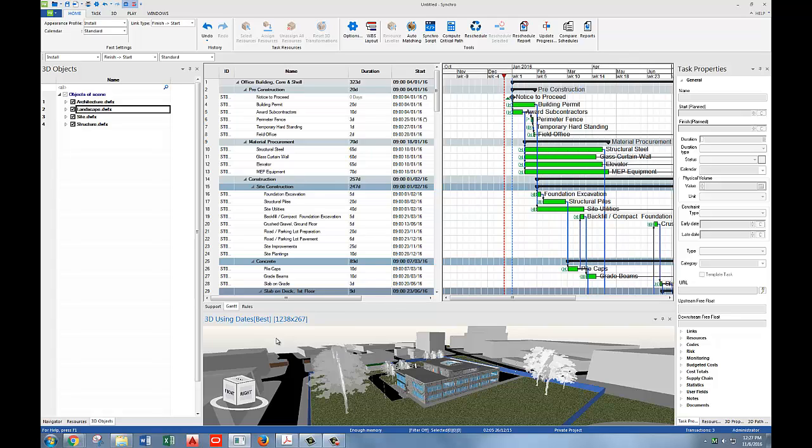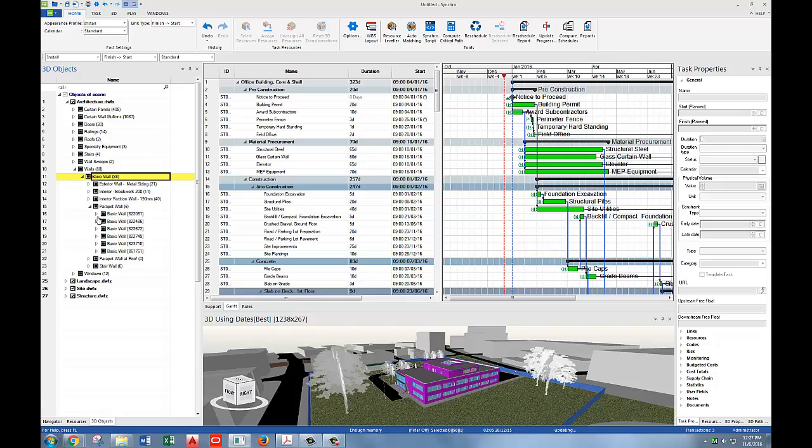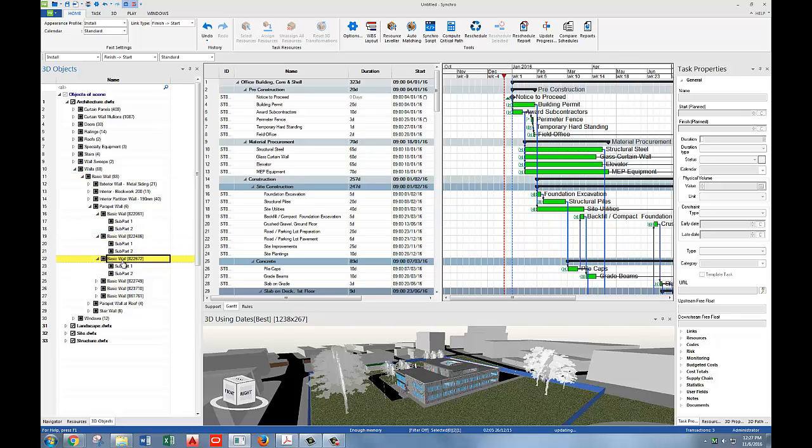So you should have imported your two new files. So over here where our 3D objects are, let's go to architecture, expand the walls tab, basic walls, parapet walls, basic wall again. So if we look right here, we can see that underneath each one of these basic walls, they have been given two subparts. Obviously, subpart 1 is the same as this subpart 1 in the computer's eyes. The unique naming convention is that basic wall with this number.